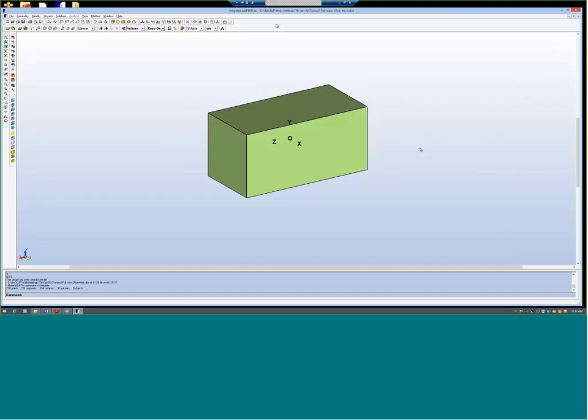Once you put an artificial truncation of the region around it, on that truncation they put the electromagnetic potential at 0, so the fields we are calculating outside may not be very accurate. So the boundary element method is the best method for this application.